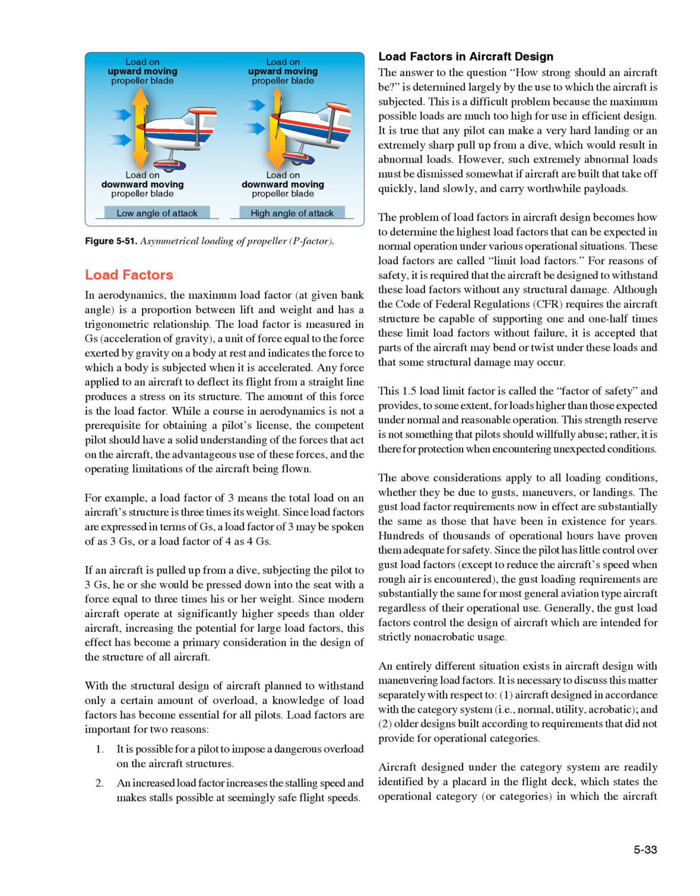For example, a load factor of 3 means the total load on an aircraft structure is 3 times its weight. Since load factors are expressed in terms of Gs, a load factor of 3 may be spoken of as 3 Gs, or a load factor of 4 as 4 Gs. If an aircraft is pulled up from a dive, subjecting the pilot to 3 Gs, he or she would be pressed down into the seat with a force equal to 3 times his or her weight.